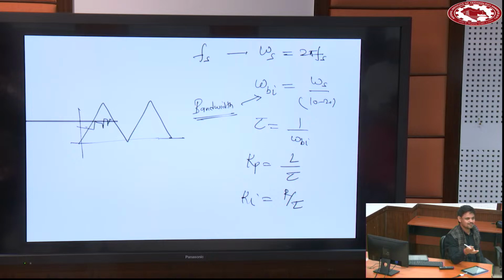Because it will not. It's something like that: I tell you up, down, you are able to follow my instructions. If I tell you up, down, up, down very fast, you cannot follow. You have some limitations. That limitation is the switching frequency. The carrier wave is compared with the modulating wave, and then some pulses are generated. Those pulses decide what current will be there. And switching will happen here.